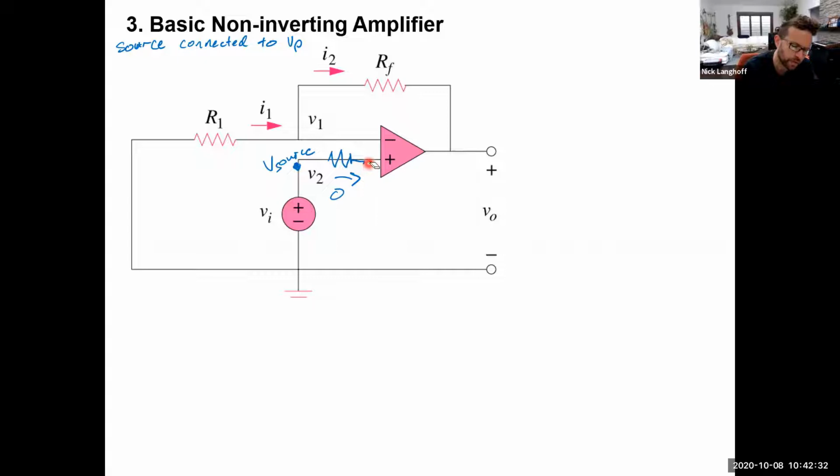Sometimes people do put a little bit of resistance in series feeding into the inverting terminal or non-inverting terminal. And that's just done for various design constraints or accommodations. So let's then derive the relationship for this common op-amp block, and we'll do it using the golden op-amp, OA for short, rules.